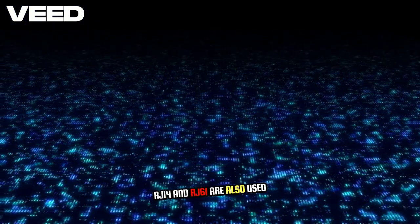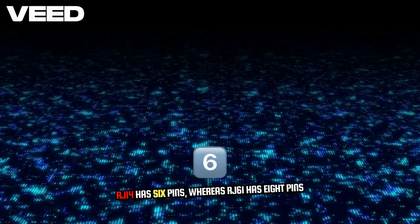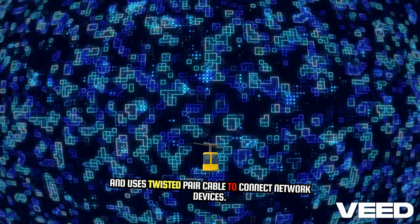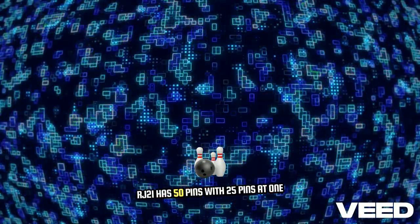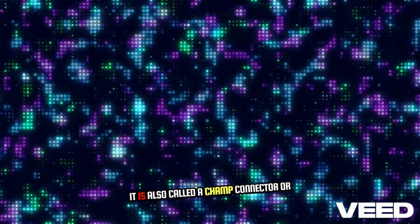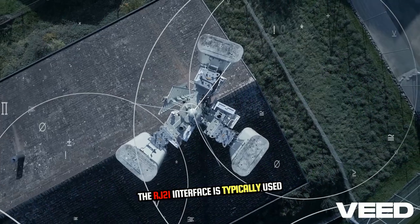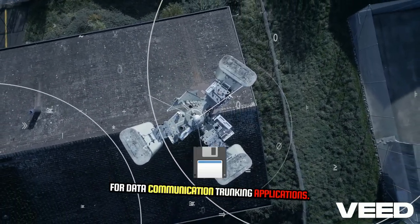RJ14 and RJ61 are also used in telephone lines like RJ11. RJ14 has 6 pins, whereas RJ61 has 8 pins and uses twisted pair cable to connect network devices. RJ21 has 50 pins with 25 pins at one end and 25 pins at the other end. It is also called a champ connector or Amphenol connector, named after the connector manufacturer. The RJ21 interface is typically used for data communication trunking applications.